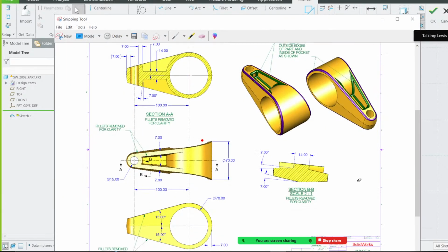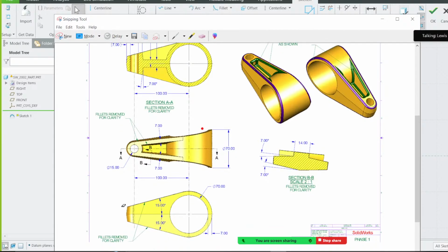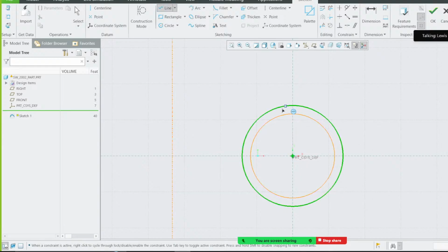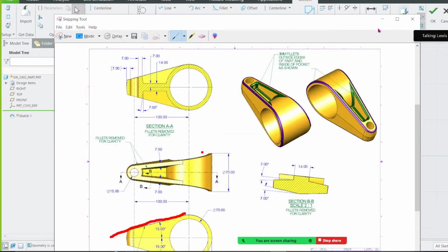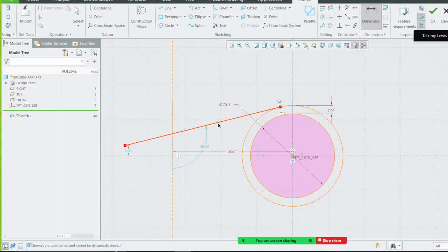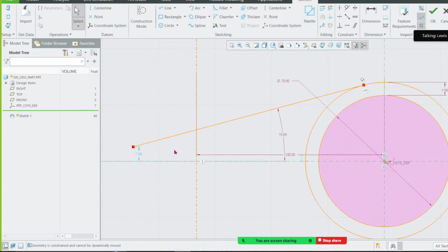Next, we have now this one here. You can see this line is tapered. To continue, let's first create that line, tangent to this and tapered. Let's first create tangency here, because we know the angle is 15. Let's capture the angle here from here. Use 15. But now we do not know the termination, where it is terminating at.